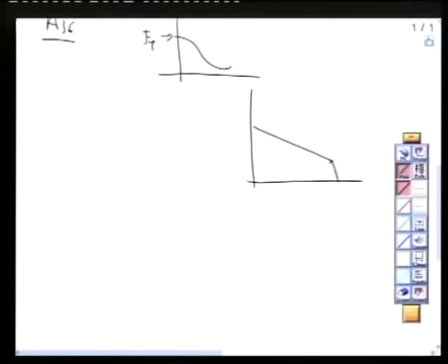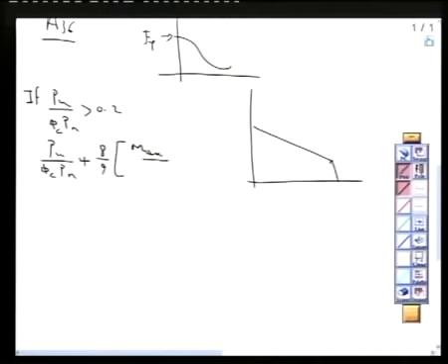And the equation for this curve was: if Pu divided by phi c Pn is greater than 0.2, then Pu divided by phi c Pn plus 8 divided by 9 of Mux divided by phi b Mnx plus Muy divided by phi b Mny is less than or equal to 1.